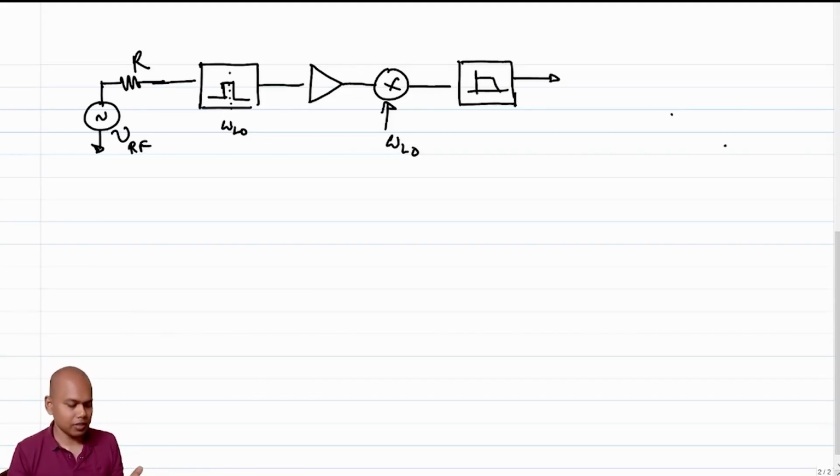One characteristic of transistors is that you have capacitances between each terminal of the transistors. So, as it turns out, no two ports of a transistor are perfectly isolated, right? If you have a signal in one port, you are going to have some fraction of the signal in another port, even if you have multiple transistors connected to each other, simply because the signal will find a way of going to the other port.